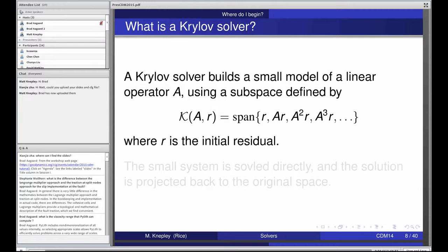The problem, you might ask, why don't we always use direct solvers? We don't, because the memory requirements become onerous, and in fact, you just run out of memory before you can solve practical problems that you might want the answer to. And this is why we turn to iterative solvers. Now, sometimes iterative solvers are also faster than direct solvers, but not all the time. But definitely, they always take less memory, and that turns out to be the real limiter.